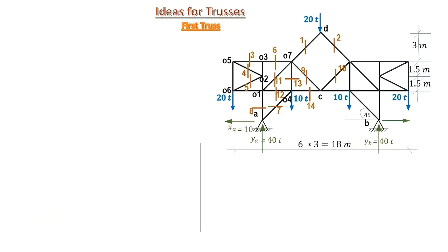To proceed with our truss and compute members 3, 4, and 5, let us start with member 3 and revise our K-truss. We have this snaky section S2 passing by 4 members: member 3, member O3 O2, member O2 O1, and this horizontal member at the bottom chord.